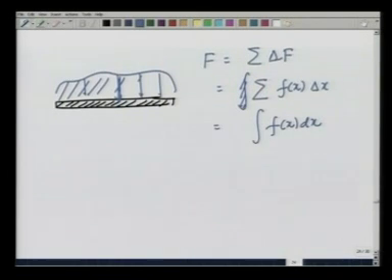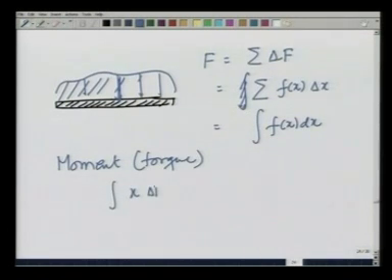How about the moment or the torque created by this force? That is obviously going to be x delta F integrated, which is nothing but the integral of x f x dx. This is the torque.